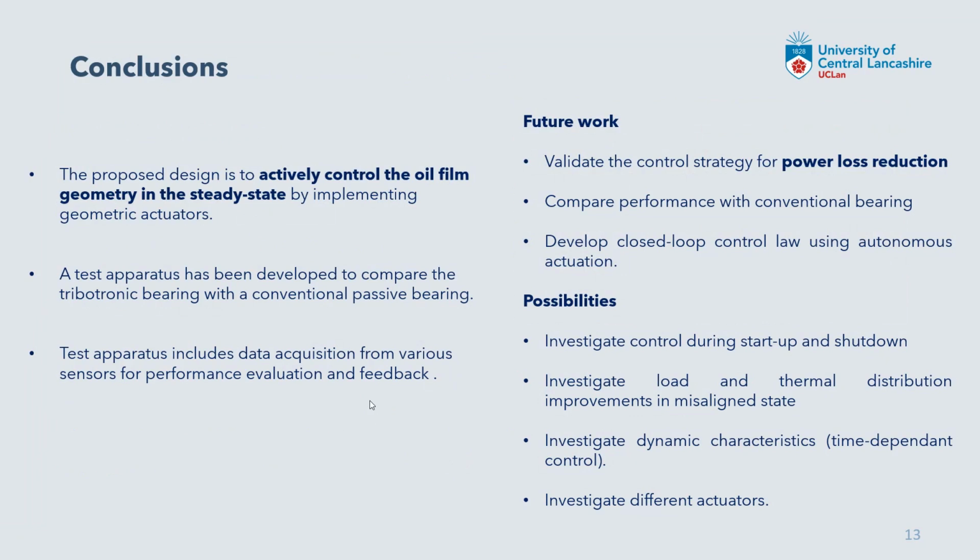And there are further possibilities, a lot of possibilities with this test rig, investigating control during startup and shutdown periods and how that influences maybe the lift off or the friction during these conditions. Investigating load and thermal distribution improvements by independent pad control, and also maybe in the future modifying to be able to investigate dynamic characteristics and time dependent control, and also investigate different actuators in the future.